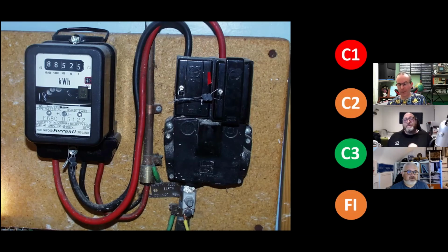So here's one for you, gents. I'm going to throw something at you. According to the cutout guidance note for EV installers, that cutout is a black plastic, circa 1960 to 1990s. If an installer is presented with this type of cutout, they must assume the fuse size is 60 amps. If the installation designer's calculations confirm the installation total will not exceed 60 amps, there is no need for a DNO assessment, and the EV install can proceed as appropriate.